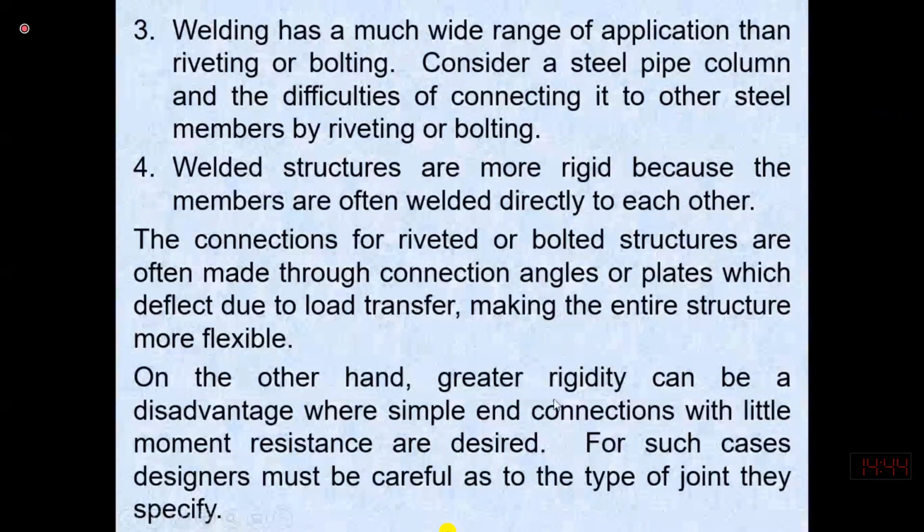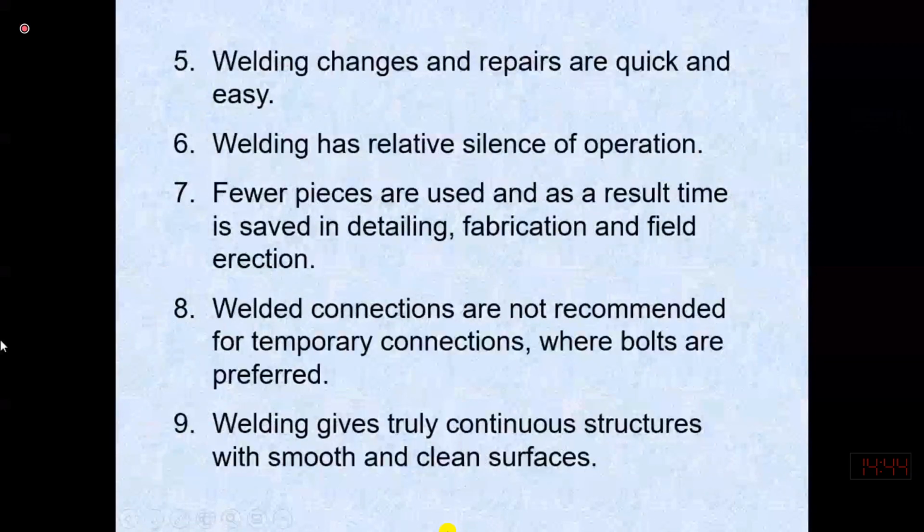So it means that the welded connection may be more rigid as compared to the other types of connection. On the other hand, greater rigidity can be a disadvantage where simple end connections with little moment resistance are desired. So sometimes extra rigidity may have some disadvantage because the behavior of the structure may become brittle. Welding changes or repairs are quick and easy. So if there is a welding failure, we can easily repair it.